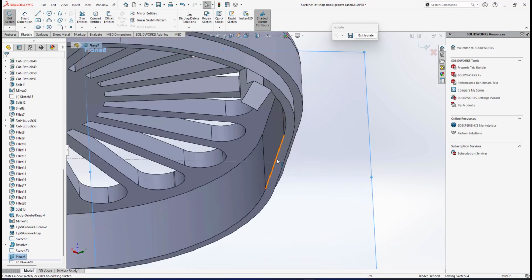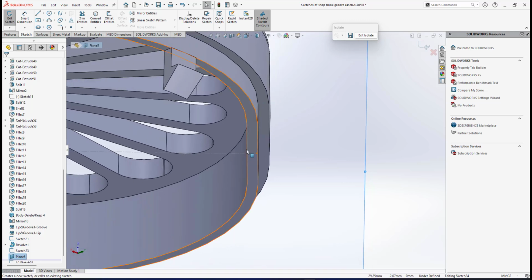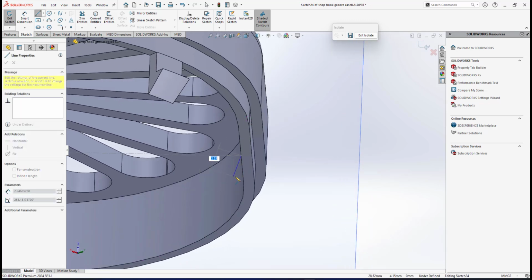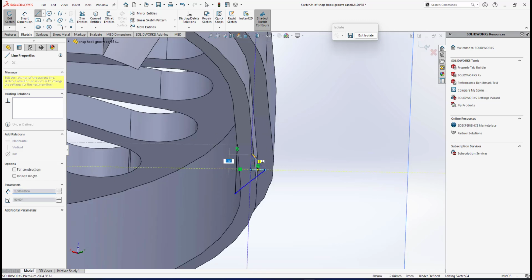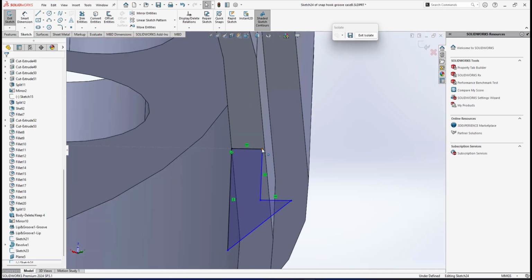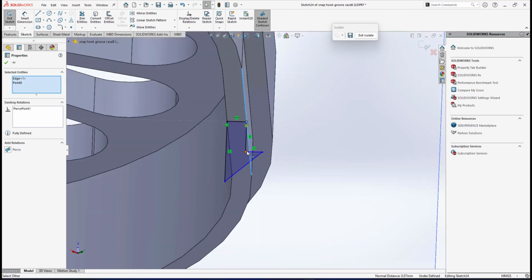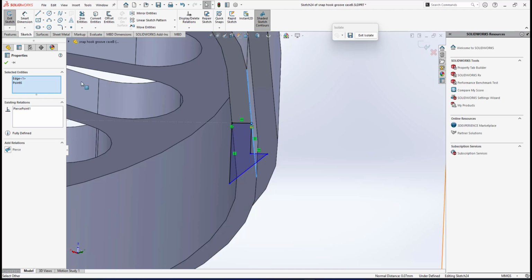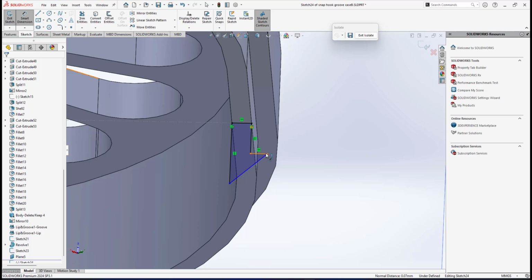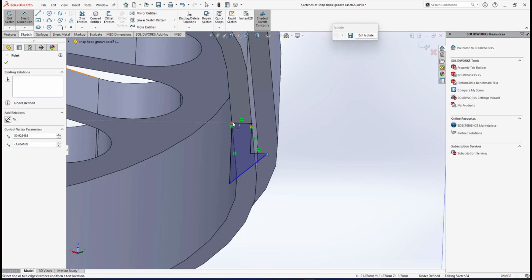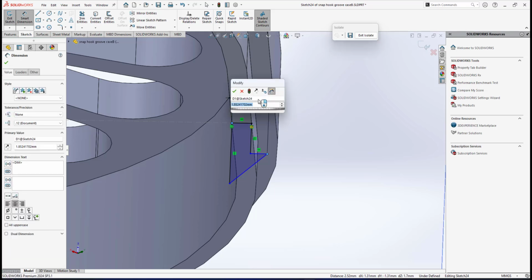My sketch profile is similar but it's like this. If I draw the line like this, make sure it is vertical. So I will draw the same arrowhead shape, and it goes like this, and like that. Okay, this is the second shape. And this line and this one I will make here, so it means the thickness is 1. One thing is that the height from this point to this point is not 2. The dimension I want to go for is a little bit shorter. From this point to this point, the vertical dimension I will go for 1.5.